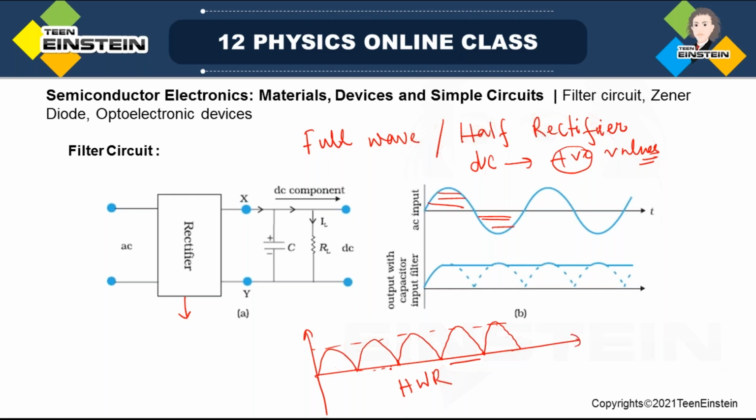But the problem is, you look here, we are getting DC signals or voltage out of AC, but the voltage is pulsating. Pulsating in the sense, if you look, this is the full wave rectifier output. This is the pulsating voltage. That means it has its value 0, it increases up to a peak value, then again decreases to 0, again increases to peak value, decreases, like that.